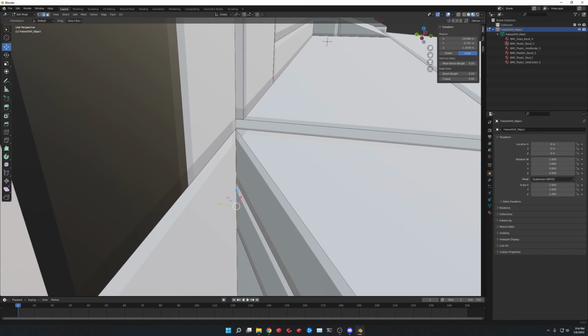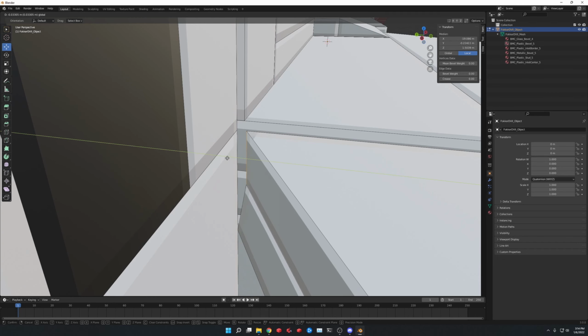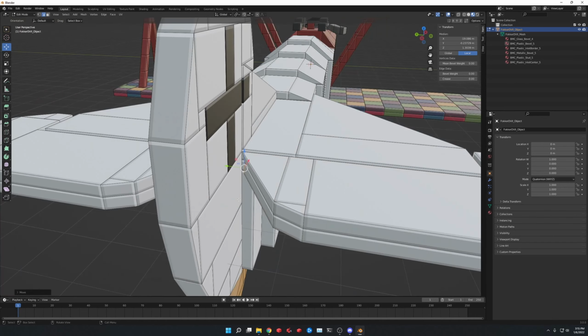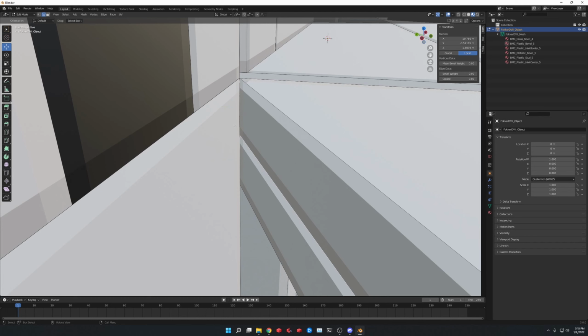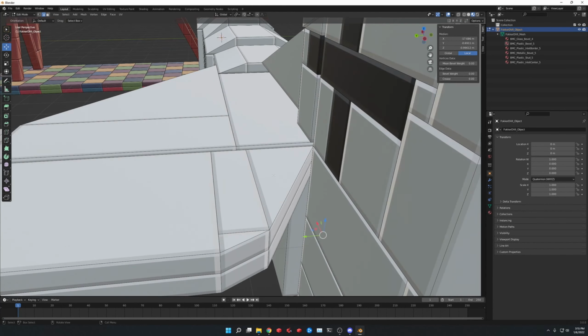And this time I'm just going to do what I've done before and select the edge and do mesh split faces by edges. And now I'm going to, yeah, there we go. This is what we were looking for. This behavior where we can actually independently move these edges. Oh, beautiful, beautiful. So to make it easier, I'm going to try to select both of these at the same time. Okay, there we go. I'll move it, yeah, just right there. Okay, let's see if we can repeat that on the other side.